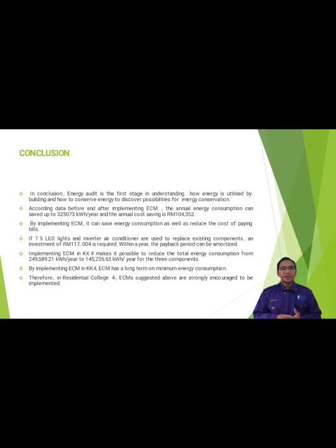If T5 LED light and inverter air conditioner are used to replace existing components, an investment of RM 117,004 is required. Within a year, the payback period can amortize. Implementing ECM in KK4 makes it possible to reduce the total energy consumption from 249,589.21 kWh per year to 145,236.63 kWh per year for the three components. By implementing ECM, it can save energy consumption as well as reduce the cost of paying bill.